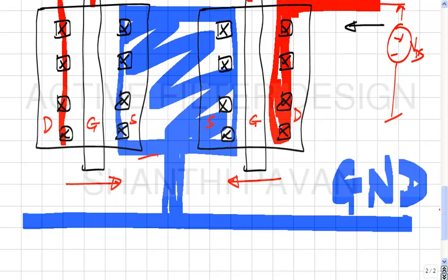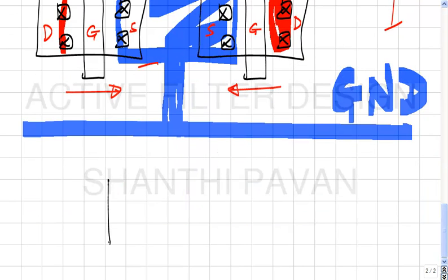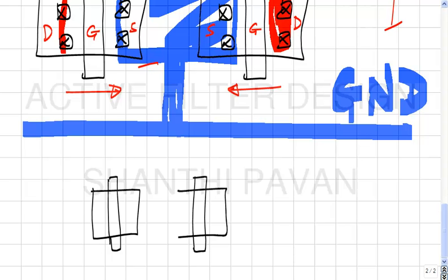Okay. So to fix the problem, one could say, okay, we lay out the transistors like this, where this is DGS, but this has the problem of unwieldy aspect ratio, because if W by L is much larger than 1, this being W and this being L, this transistor will be skinny and tall, and that's no good.